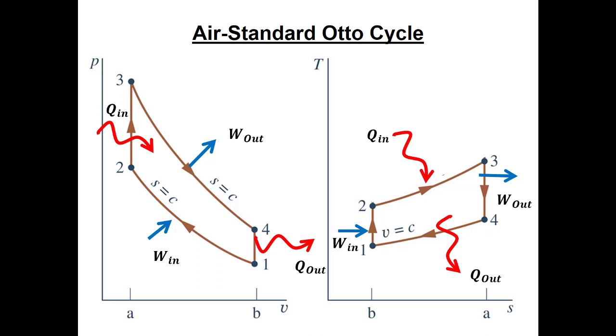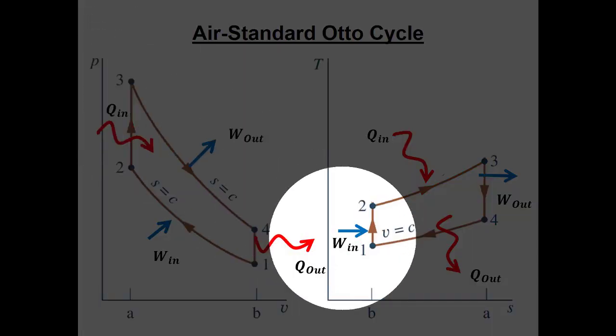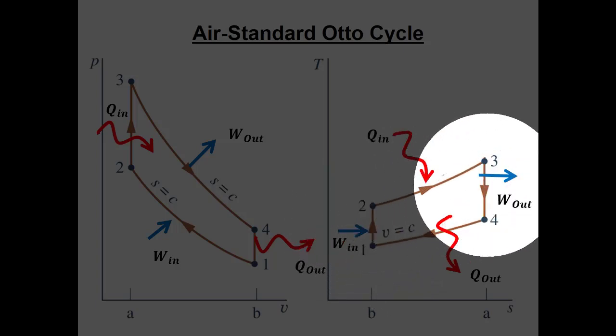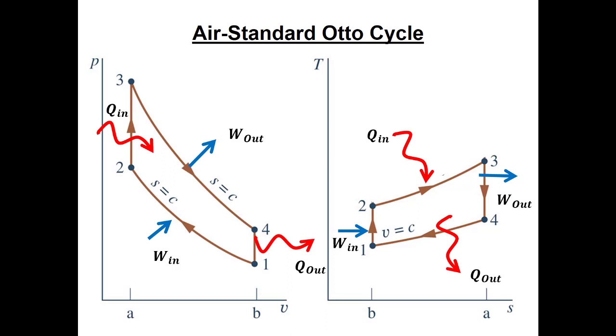The other thing, because here the working fluid is air, we need to be able to identify the processes where they're isentropic, and those are going to be the processes where we're only doing work. They're also the processes with vertical lines on a TS diagram, whether it's going up, like from state 1 to state 2, or down from state 3 to state 4.